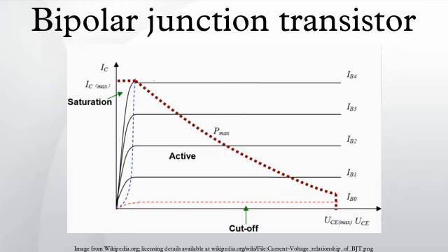Applications: the BJT remains a device that excels in some applications, such as discrete circuit design, due to the very wide selection of BJT types available, and because of its high transconductance and output resistance compared to MOSFETs. The BJT is also the choice for demanding analog circuits, especially for very high-frequency applications, such as radio frequency circuits for wireless systems. Bipolar transistors can be combined with MOSFETs in an integrated circuit by using a BiCMOS process of wafer fabrication to create circuits that take advantage of the application strengths of both types of transistor.